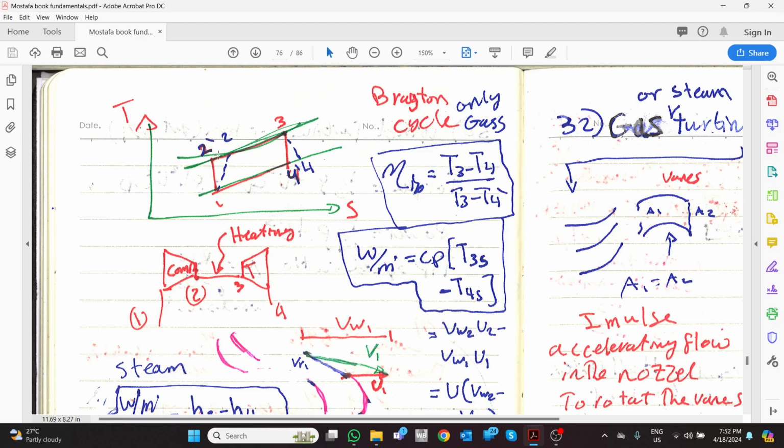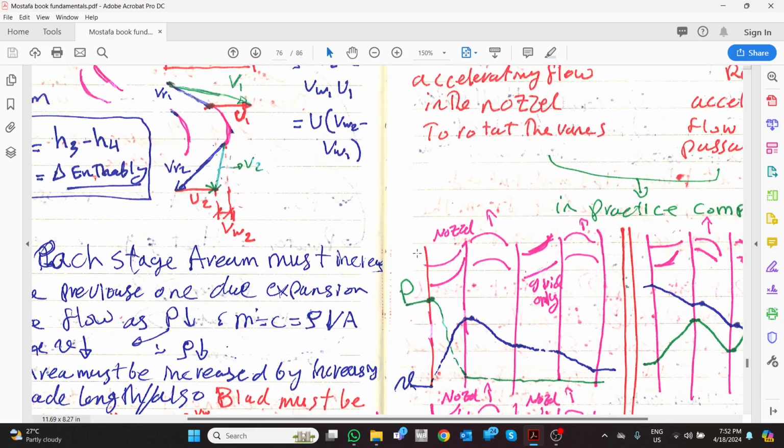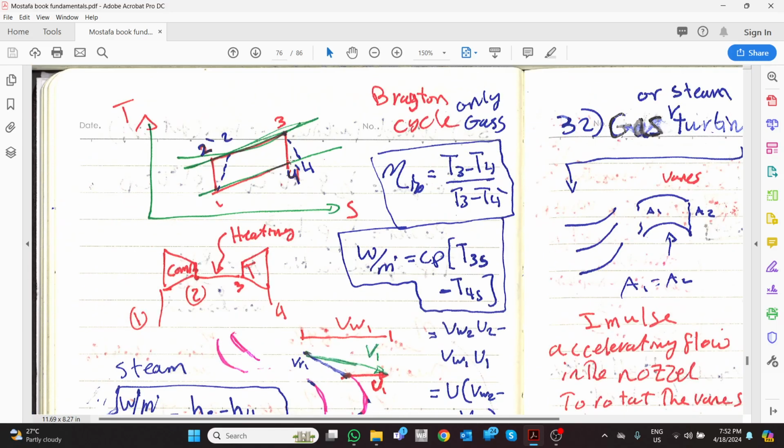What we are trying to get, like what we discussed before, is the isentropic efficiency in the turbine. So we know from 3 to 4, 3 is the inlet to the turbine, 4 is the outlet from the turbine. If this is the actual one and this is the isentropic one, same as the efficiency, we can apply it. The total we have is 3 minus 4, temperature 3, of course multiplied by Cp and m dot, and that is the efficiency.